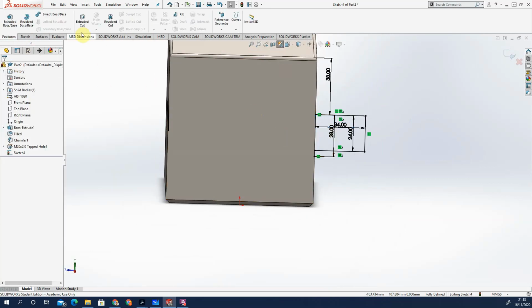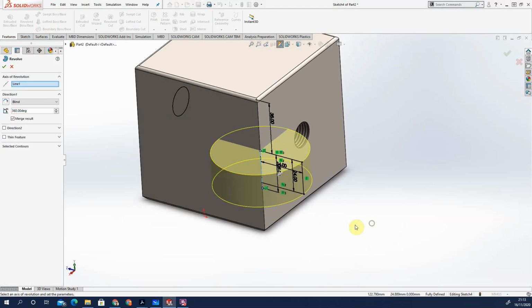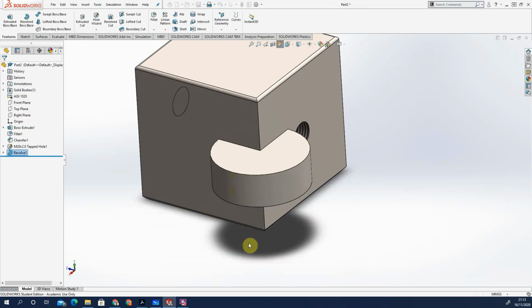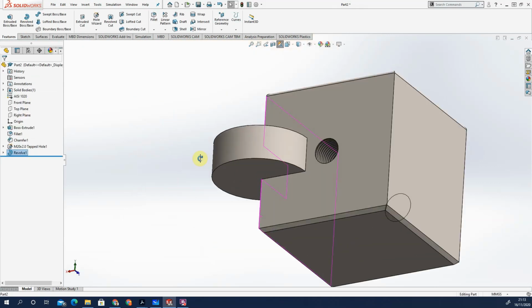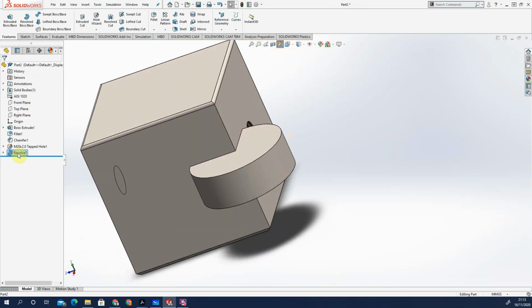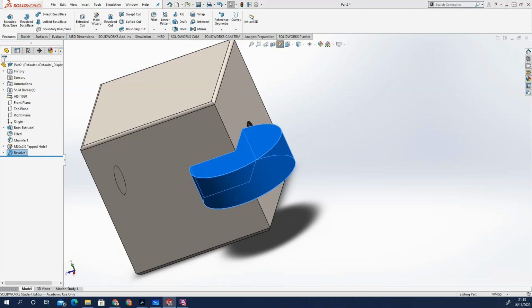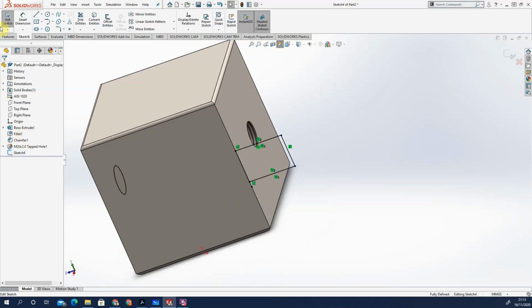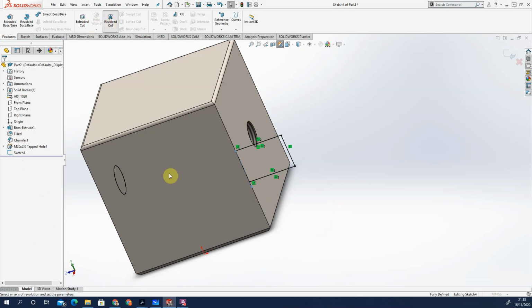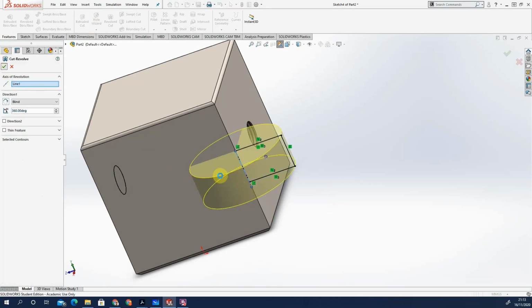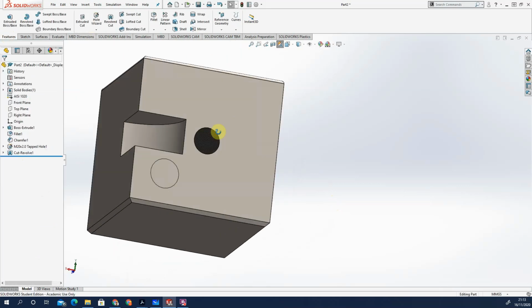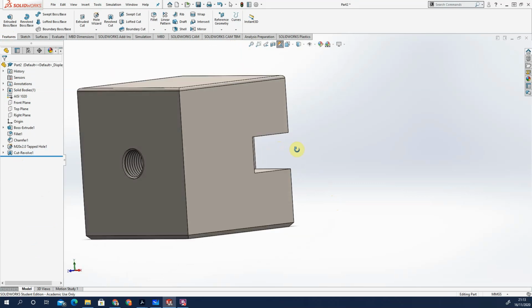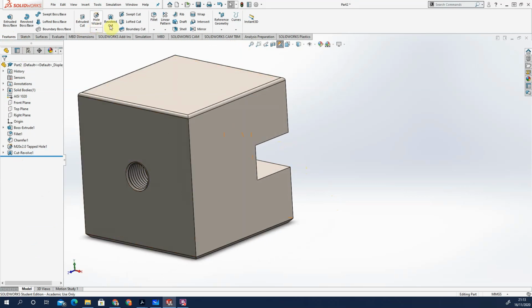Okay, happy with this. Now I'm going to go to features. Normally if you're going to want to revolve, I could say, yeah, I want to close it off, I could add it in, revolve around my line, and I can add that particular feature, or I could now actually delete this, re-edit the sketch, go into features, do a revolve cut instead. I have a nice sort of chunk taken off. So that's basically looking at revolve base and revolve cut.